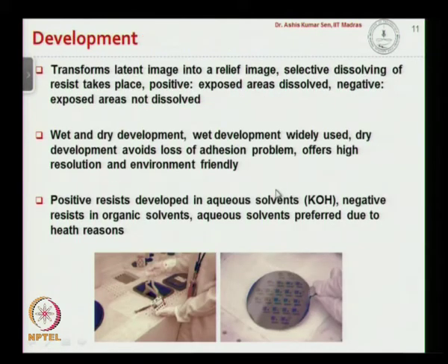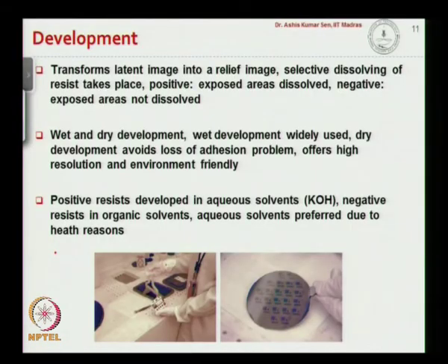So once we have done the post exposure bake, then we want to go for development. So you dip the wafer into a developer solution. The development process actually transforms the latent image into a relief image.